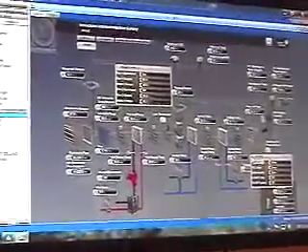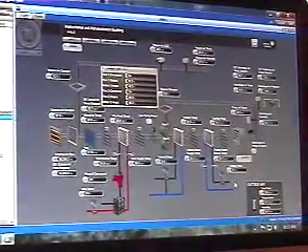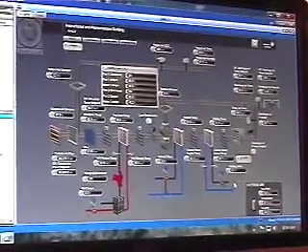We then stay in that mode. We have a minimum runtime of 60 minutes in that, because once you turn that evap media on, it's not instantaneous. It's going to take a little bit for those pads to get wet. The more they get wet, the better they work. After an hour, if we're still above set point,